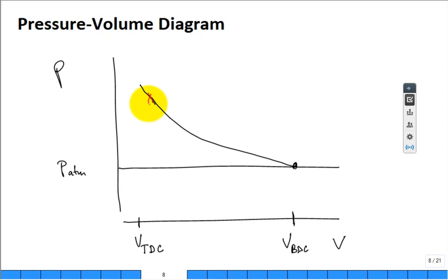Anybody use a timing gun? Yeah, you set it with the mark on the crank, but now that's kind of old school. You used to have to rotate the distributor. Now that's kind of gone. All the controls are electronics. But it fires a little bit before. Now, if you're running at 5,000 RPM or 8,000 or 10,000 RPM, it could be firing 40, 50 degrees before top dead center. It's going so fast. But those are changing. Let's think it fires a little bit before top dead center.